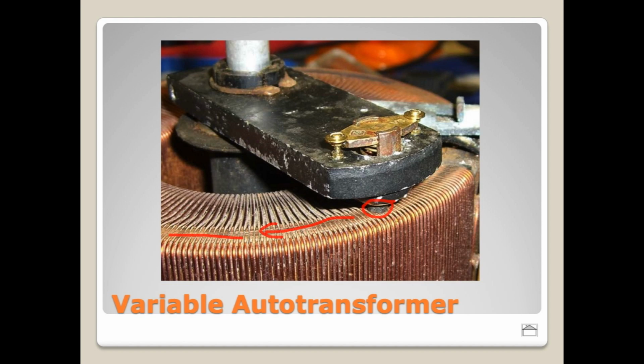And so the owner was very cost conscious, really wanted to save some dollars when he could. And so he would always, in the evenings, go downstairs and say, well, hey, if there's nobody here, we're going to dim the lights. Now, he installed traditional dimmers, right? The kind of thing that you would go buy at Lowe's or Home Depot that throws harmonic garbage onto the lines.